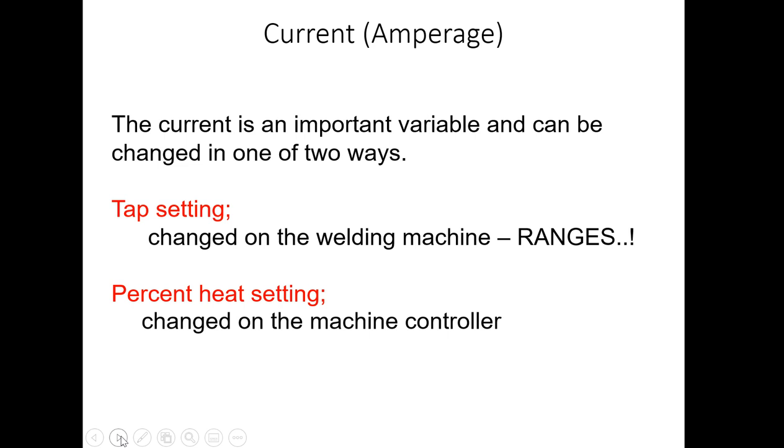Think of it like a range, the ranges that you're going to set it in. And you never want to set a range to be maxed right out. That's why they give us these tap settings, so we can figure out what range it's going to work at, because you can't just give a person a transformer and have all the ranges be met accurately.